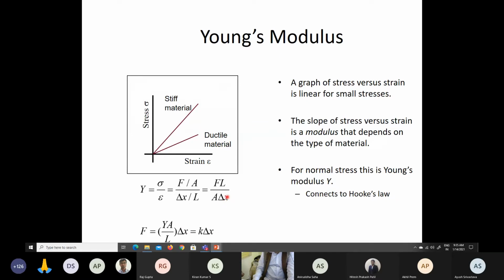So if the force divided by the displacement, resistive force per unit displacement, would come out to be AE by L. Okay? So it is the Young's modulus, the length of the specimen and the cross-sectional area that contribute towards the stiffness of the material. Stiffness can be defined also as the resistive force per unit deformation. That way also. So people who have studied finite element analysis are quite aware of the term AE by L as the stiffness of a bar or a link.